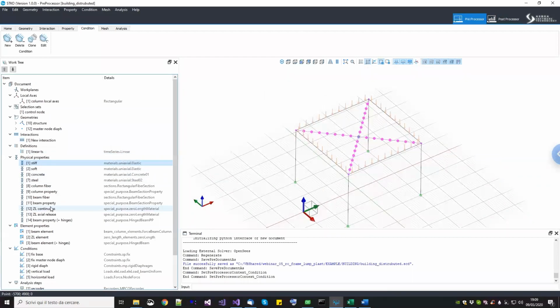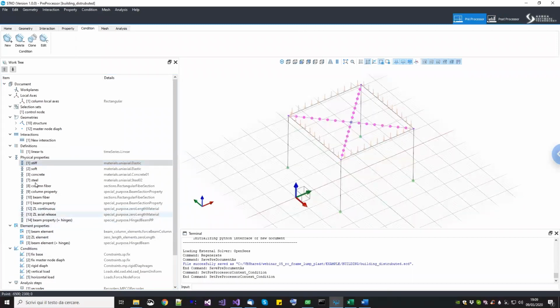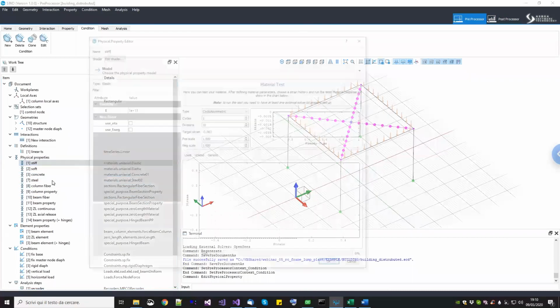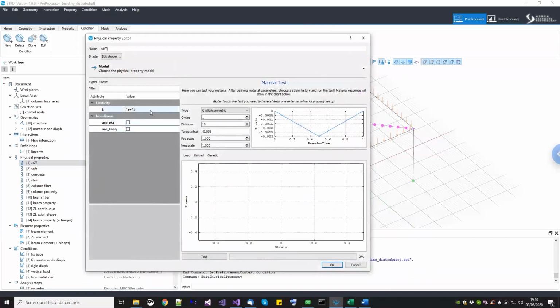Now let me start little by little. Okay, here we start, this is where you can start. So basically, if you start from this model, what do you have? You have a uniaxial material model, which is the stiff one, the same one that we used before in the column example. This stiff material model will be used every time we need a hinge, and we need to keep the continuity in one degree of freedom.